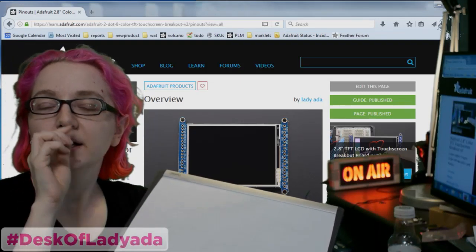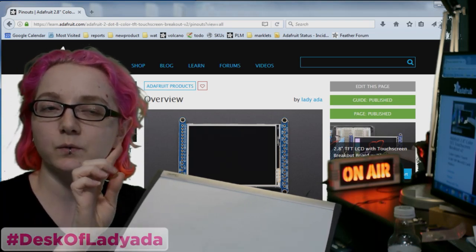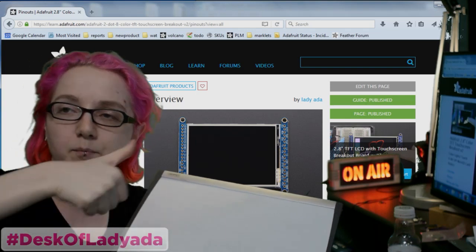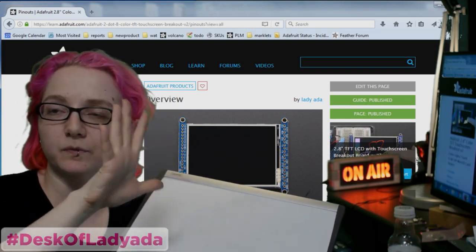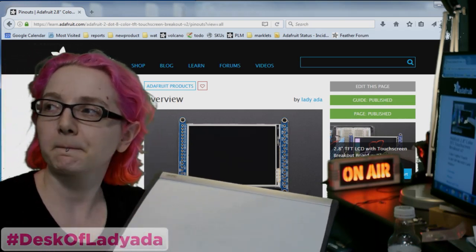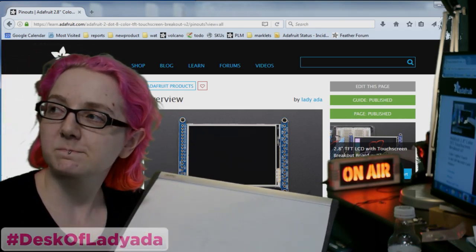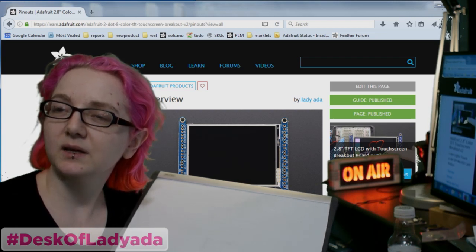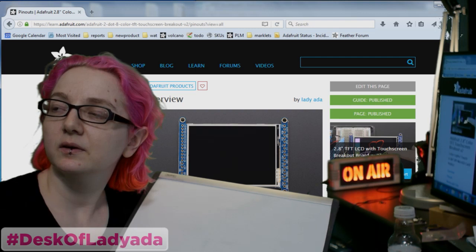You can do a little bit of pressure sensing with capacitive touch by detecting how big the touch spot is. Like the more you press, the bigger the spot. So if you have really big fingers, it'll think it's higher pressure. So for iOS, the software is detecting a press and hold, and it's using a little pager motor, and it makes it feel like a thump.